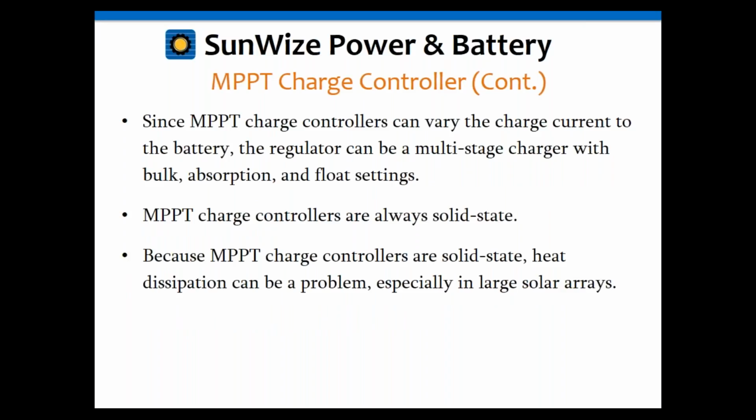Similar to pulse width modulated controllers, because they can control the charge current and voltage going to the battery, you can create a multi-stage charger with bulk, absorption, and float settings. And also, they're always solid state because they require transistors in order to do this.